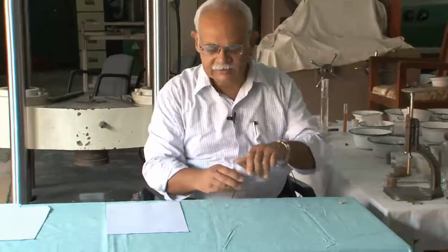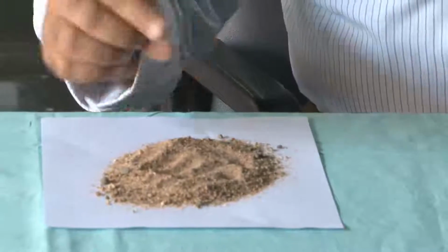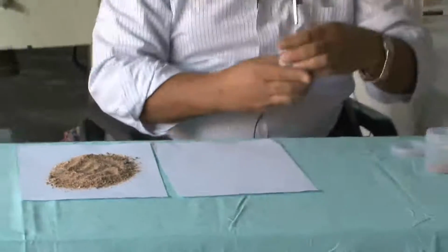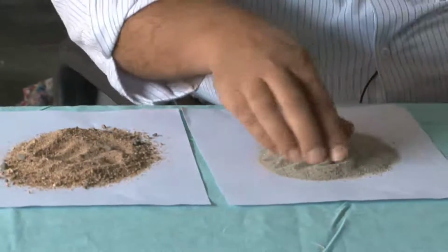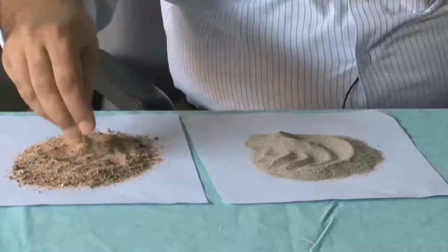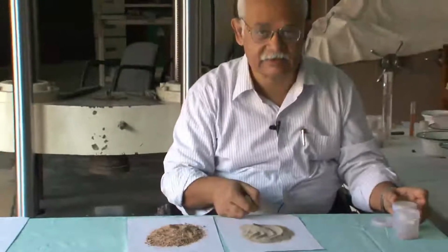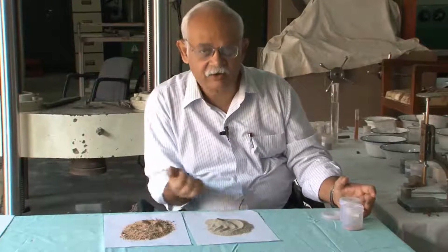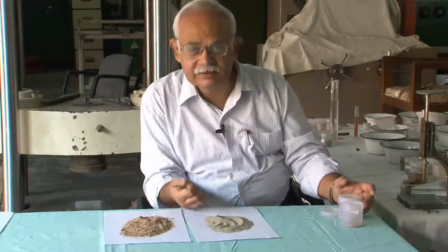Now, let us look at some samples of fine aggregate. This is one set of fine aggregates, which is what we use as, or what we call, sand. Compared to this, we have another sample of sand which looks something like this. And if we look at this, even by the look and the feel, we know that this sand is coarser than this sand. Depending on the application that we have in mind, we use the coarser sand or the finer sand. The fineness modulus of these two sands is different.